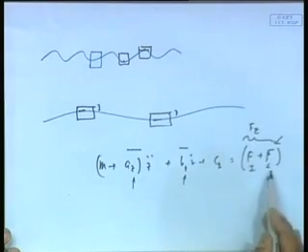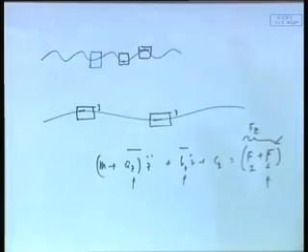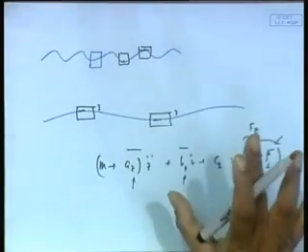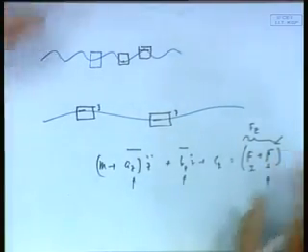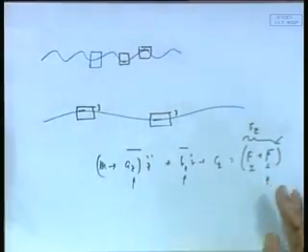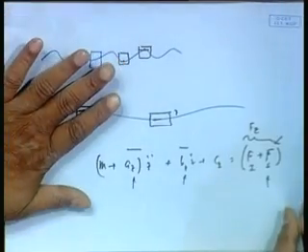So therefore this is the situation where things are critical, and my demand on calculating Az, Bz and the Froude-Krylov dynamics correctly also becomes more important. See, had it been the opposite, with the critical scenario having less hydrodynamics, I could have afforded a poor estimate of hydrodynamics, but in this situation you cannot ignore hydrodynamics. Therefore it is the hydrodynamic forces that are more important for inertia dominated motion, and also for the damping part. Okay. So this part is extremely important for us to understand.